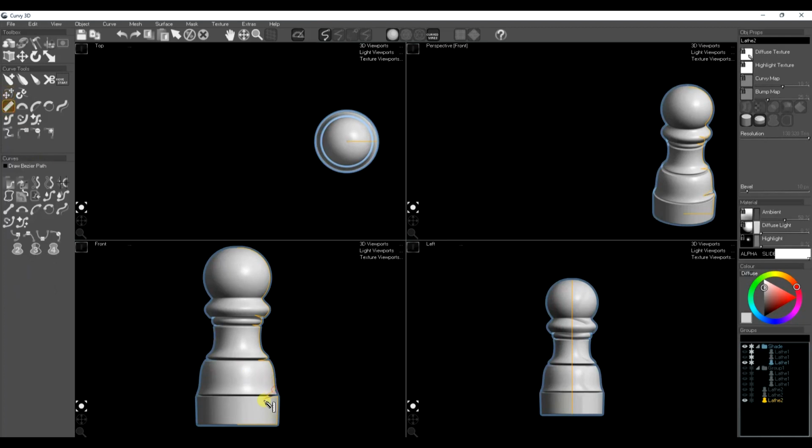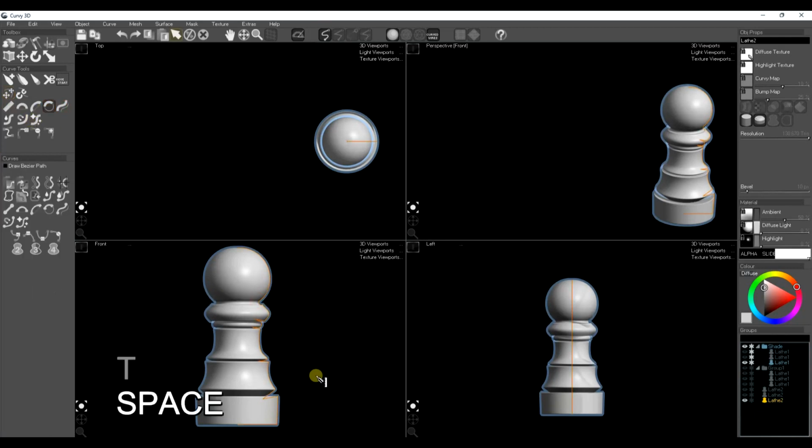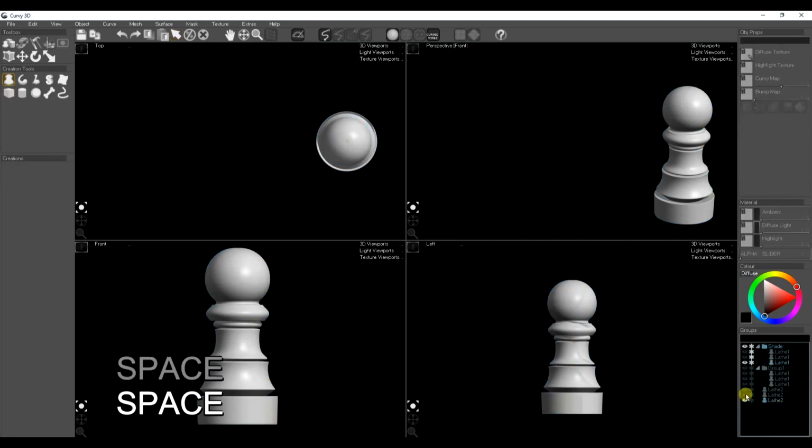So you can see we've got quite fine control of the shape now by using a mixture of curved and straight rulers. Soften up some bits, again using the curved rulers. If you press 0, the pull tool goes back to dragging the whole curve.